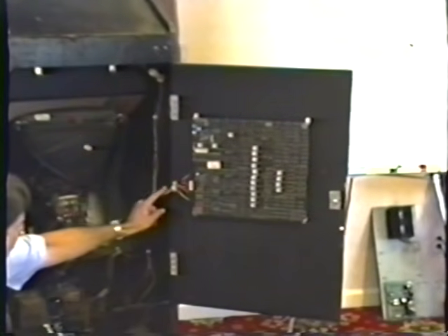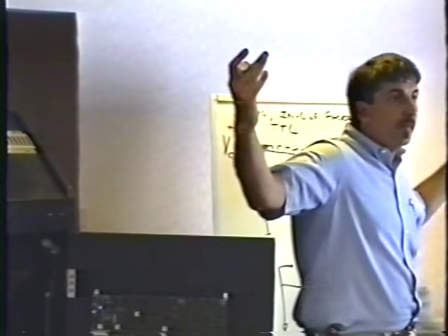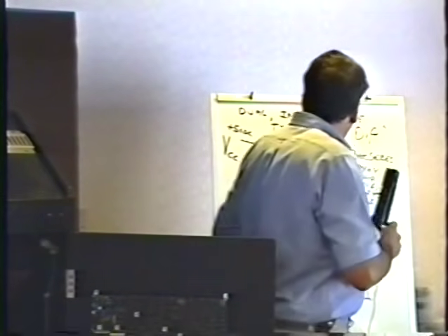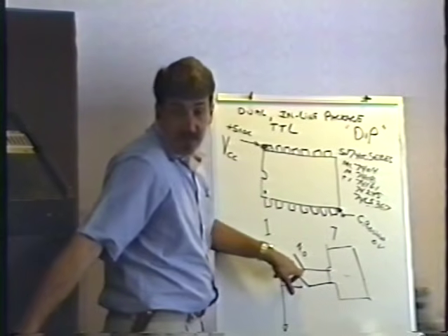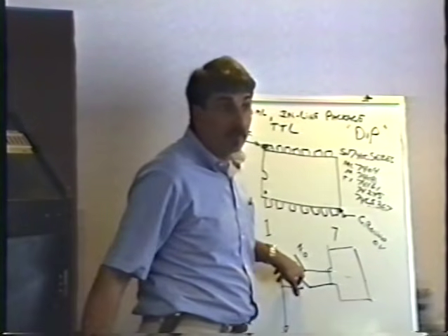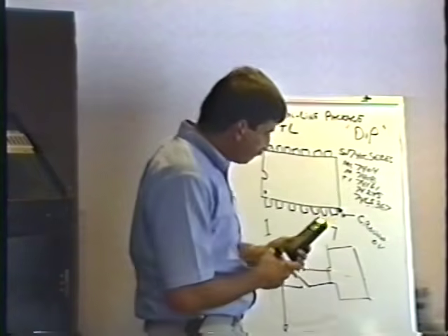If you look at the game, from here, the wire goes all the way down here, all the way down here, way up and up underneath, you know, and up to the control panel. So the wire is actually, you know, probably a meter long, probably the wire of the control panel. And it is unterminated. That is, it's sitting there just in the air, basically. It acts like an antenna, is what happens. It acts like a big, long antenna.